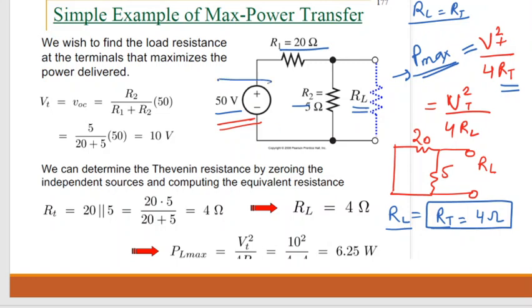That's why I make this a voltage source. I remove the voltage source and place a plain wire across this. Yes or no? No, we never put the plain wire across RL. Whenever we need to calculate IN, wait. You are saying that we need to calculate RT by the method VOC divided by ISC, right?